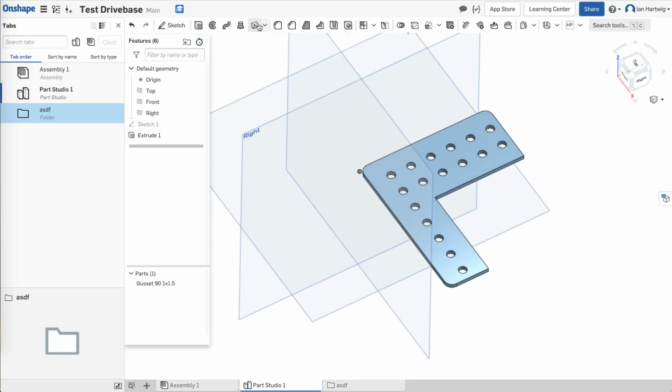So now that you're outside of the sketch, this toolbar totally changes to 3D items. You can see that on the same toolbar as extrude, you get things like fillet, chamfer, which is like a slice on the corner. You get all of your different options, like popular attributes like shell and hole that we'll talk about later.